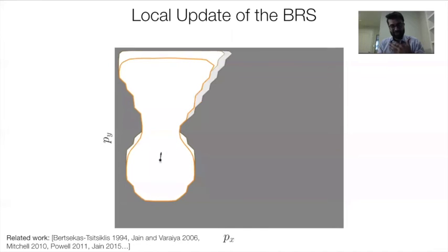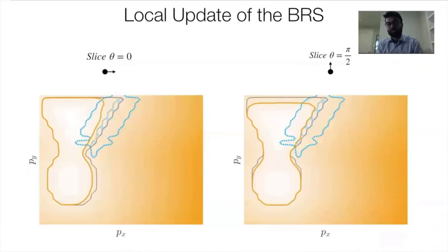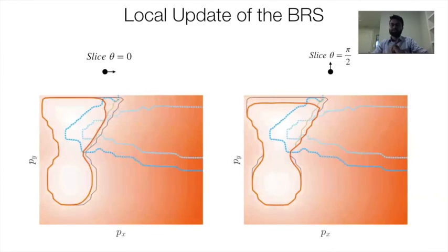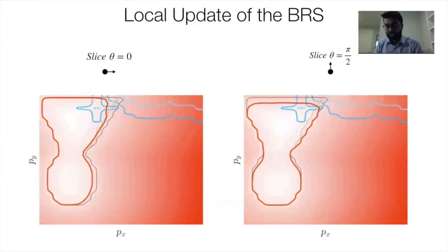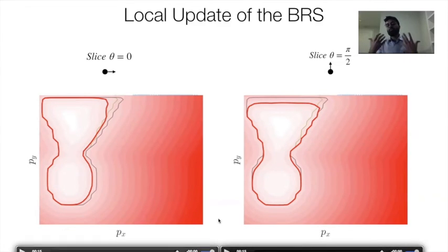In the interest of time, I will move a little bit quickly through this, just to give you a very quick intuition about the local update. Suppose this light cyan region is where we have got the new information about the environment. We can update the safe set only in this region and the region around it. Everything within this dark blue boundary is where we update the value function. Now, this is based on the principle of dynamic programming, so as you update the value function in this area, that affects the value of its neighbors, and then its neighbors, and then its neighbors. You can see this blue boundary growing in size, and we are updating the value function in more and more states. But at some point, this converges, and we get our updated value function. The nice thing about this computation is that we never touch this lower half of the state space, and that's where we get our computational savings from.